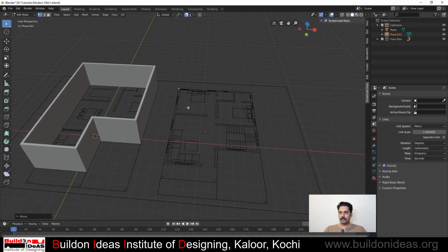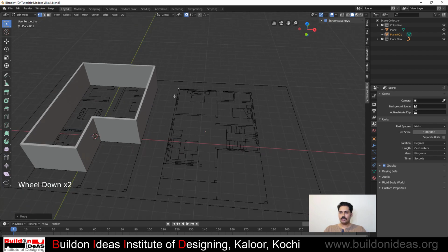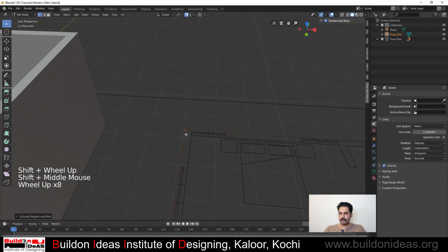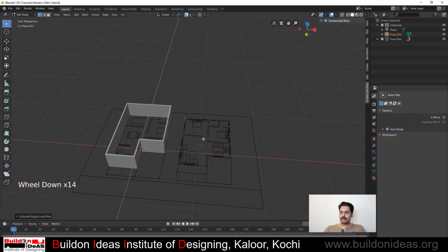So you can see there are 2 vertices in the view, but this is the origin point and this is the vertex which we have to work on. I've positioned it in one corner, and then I'm pressing the extrude button E, and snapping it to the available vertices. Just do the extrude, and you can see that when I put the last vertex near the first vertex, it automatically welds out here. This is possible only if you have auto merge ticked. This is not ticked by default. When we tick it, it is in this context menu, and then it has been merged automatically.